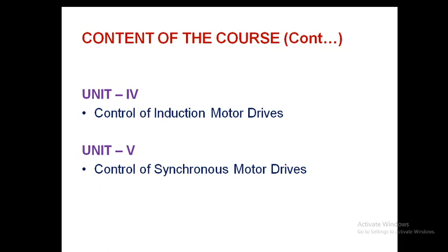In control of induction motor drives, to control the induction motors, we will see control of induction motor by using an AC voltage controller. By using the AC voltage controller, your voltage alone is controlled. To control the frequency, again frequency control of induction motor drives with the voltage source inverter, there you can adjust the frequency also.